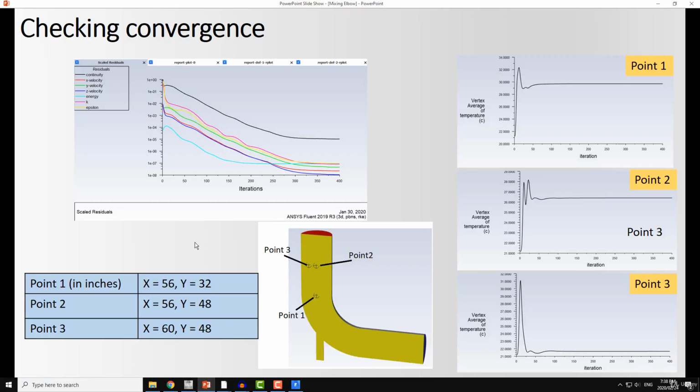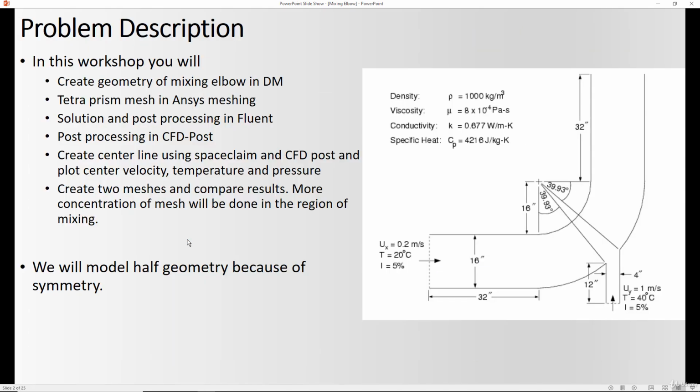And let me show you this case within the sketch. So you can see that in the x direction, if I'm making the geometry along the flow direction, the x direction, we have the length of geometry in the x direction 32 plus half of this value, which might be equal to 16.